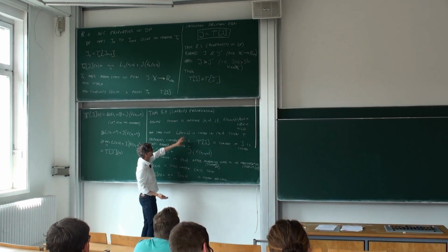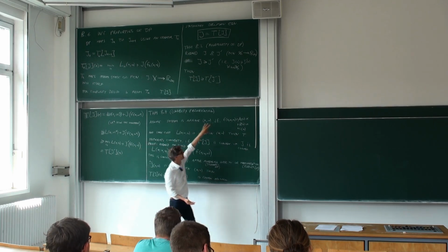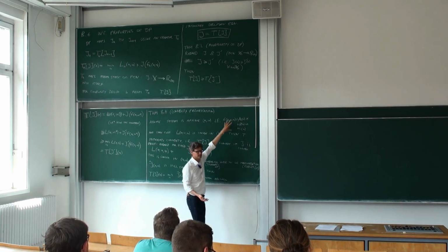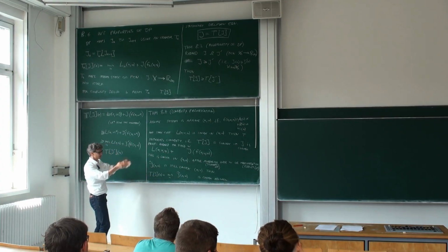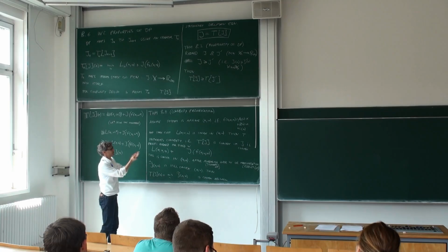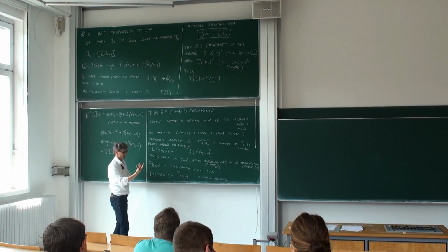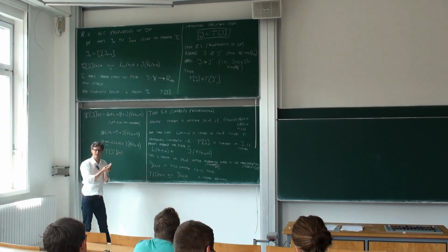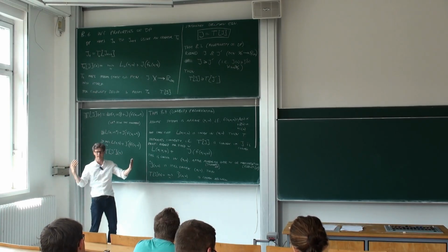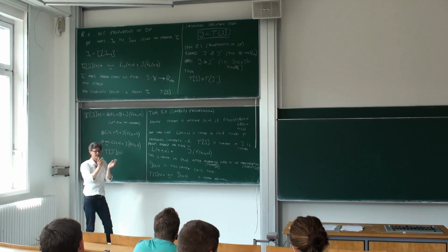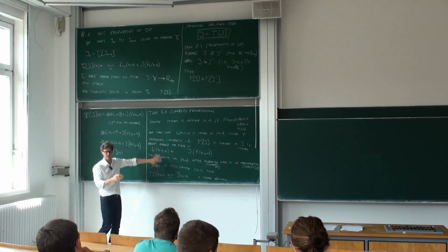So if we have a convex quadratic stage cost and a linear system like we had there, and J was a quadratic convex function as well, then after one time step, dynamic programming will still give us a convex function. So if you apply it infinitely many times, which we did for the linear quadratic regulator, it will remain at least positive semi-definite. We just proved convexity, right?